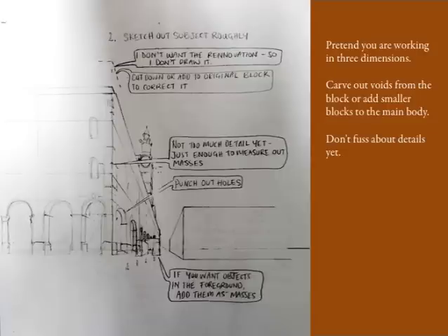The proportioned foreshortened face can now be matched to the information from the real three-dimensional object that we're drawing. The middle of the object will match the middle of the face. Features in the middle of the object will be drawn from the optical middle of the foreshortened face. It's quite simple. Once you start looking at where the features are, you'll probably find the volume you've drawn is wrong. So, now is the best time to make changes.